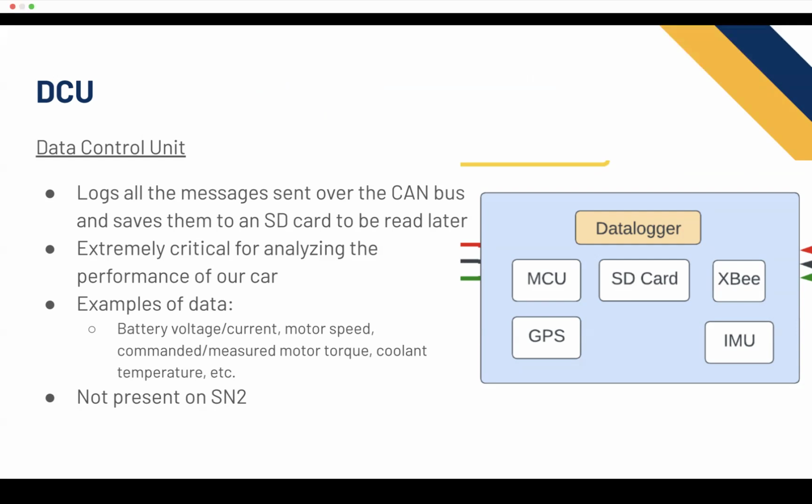You have the number of Newton meters that the accelerator actually commands, but how much torque is actually getting to your tires? There's a big discrepancy there, which we can go more into. You want to make sure that the measured torque, which is something the inverter can give you, which is basically feedback torque, is optimized to get as close to your commanded.